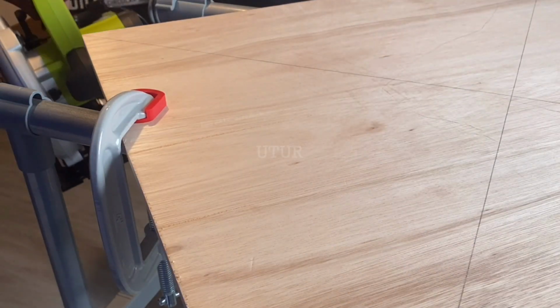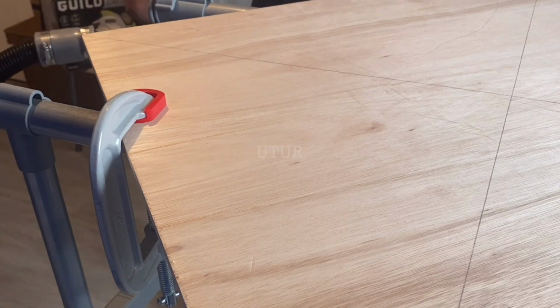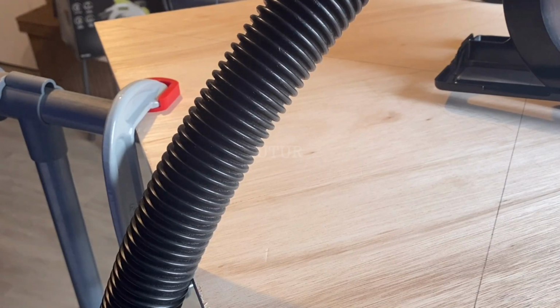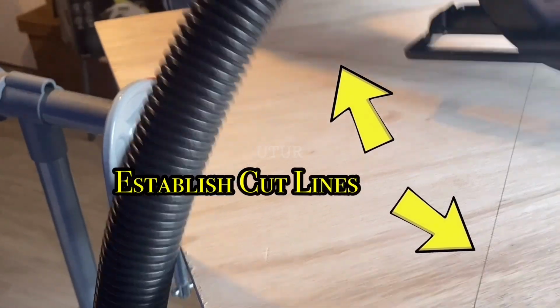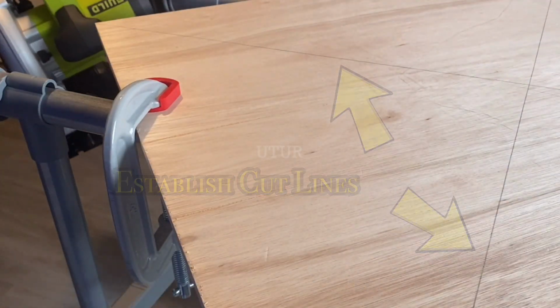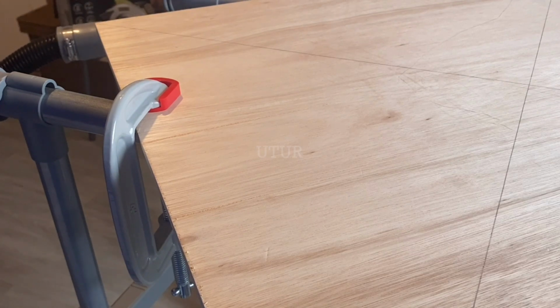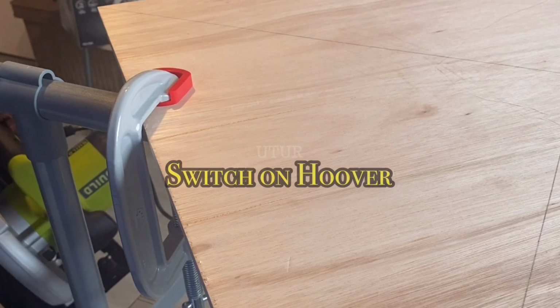The next step of the process would be to cut in line with the markings on the underside. Set the base plate of the working tool on the underside of the plywood, right at the lines of the markings. Get the saw blade spinning right before it engages the plywood, whilst the base plate is sat flush on the underside of the plywood. Do not start the working tool right where the saw blade engages the wood.